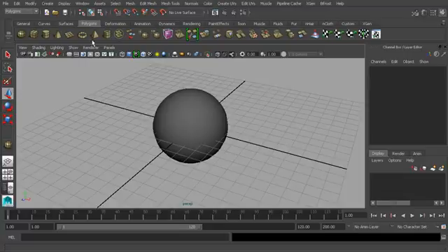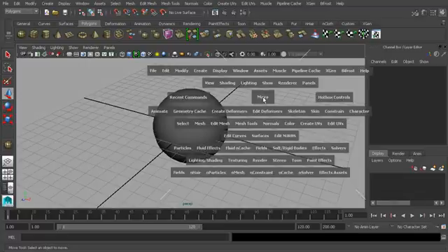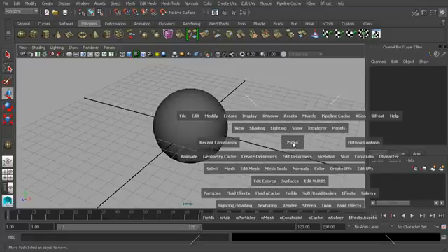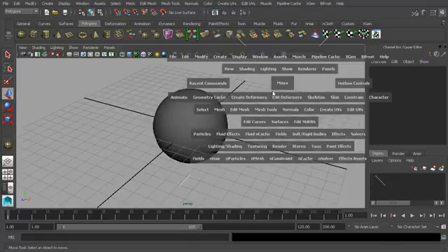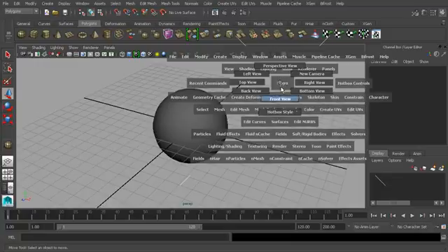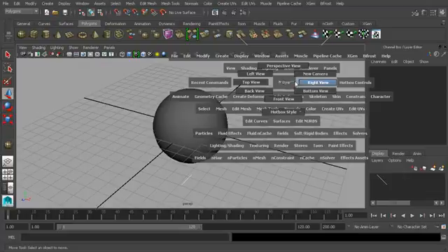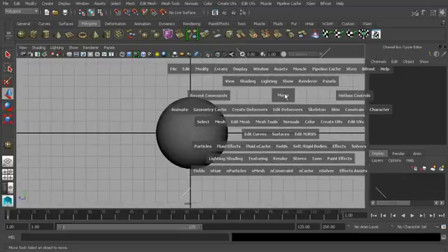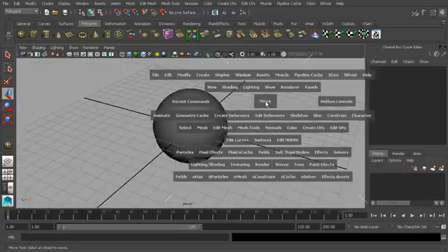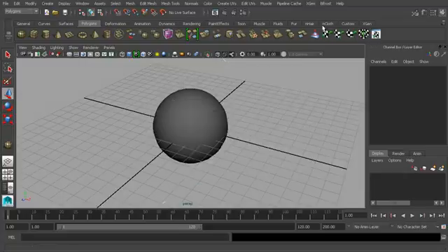Now, in addition to all of the menu items that we'll be talking about here in our viewport, we can also access something called the hotbox. So I'm just hitting the space bar over here. It's dead space, and it can bring this up. This is basically a floating menu. And then we can come in here and select. So if I click on Maya, I can select different views. I can change this view to the right-hand view, or come back and change it to perspective view.